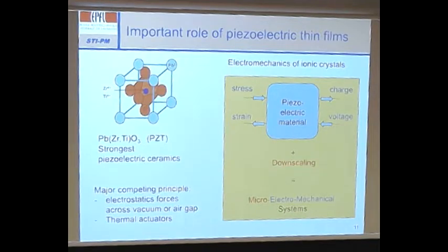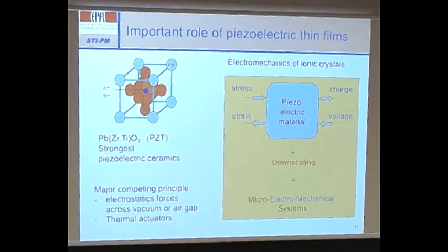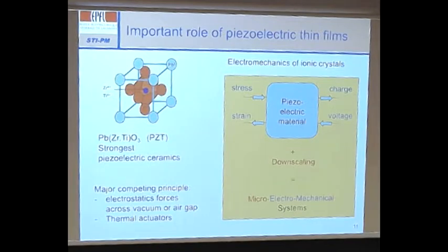That gives stronger materials, but it's always the same family. And this is the standard actuator you buy, let's say, from Physik Instrumente. You buy a linear actuator. Of course, it's made with that, except if you wish, I think they have one product lead-free. You have to put in some more voltage for the same stroke, but they have one. But okay, so that's this material.